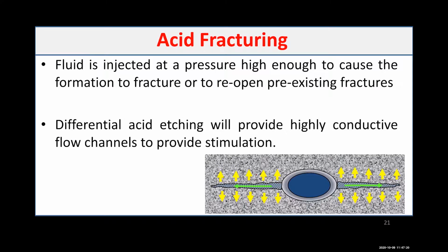The last treatment that I will try to cover is the acid fracturing. Here we are pumping the acid at higher pressure, more than fracture pressure. So what will happen? We will create an actual frac. So if you pump it, you will see, like I have here, this is a sort of the frac that has been created